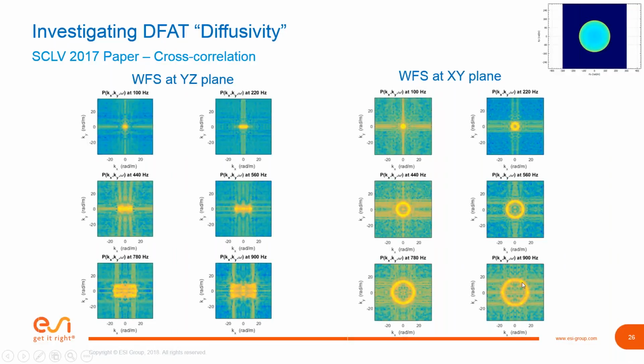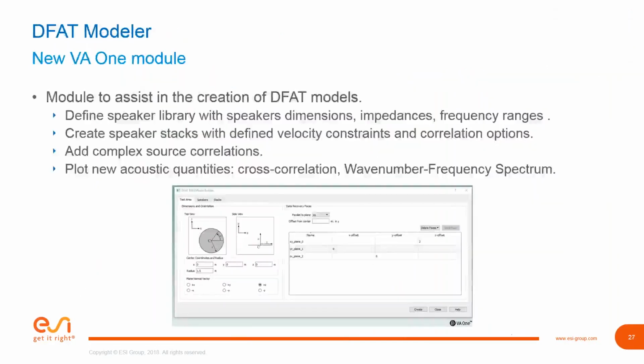And the other thing you look for is hot spots and cold spots. A hot spot means you have extra acoustic energy at this angle of propagation, and a colder, darker spot means you have less acoustic energy. Then you need to be worried that you're not properly exciting and testing the structure and the structural modes enough to qualify and prove it's going to survive a regular operating condition.